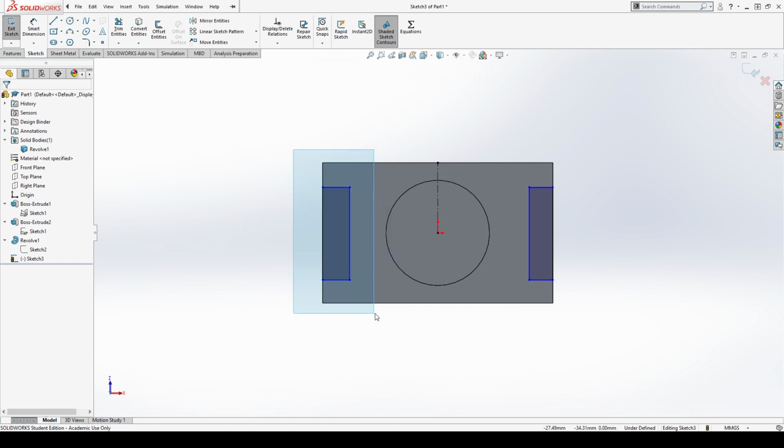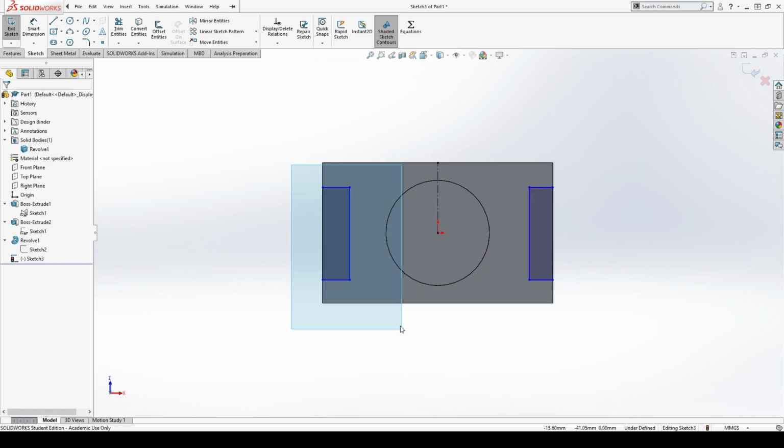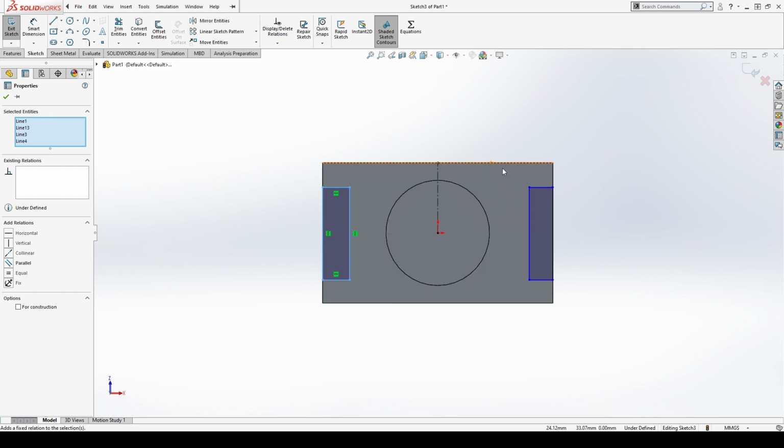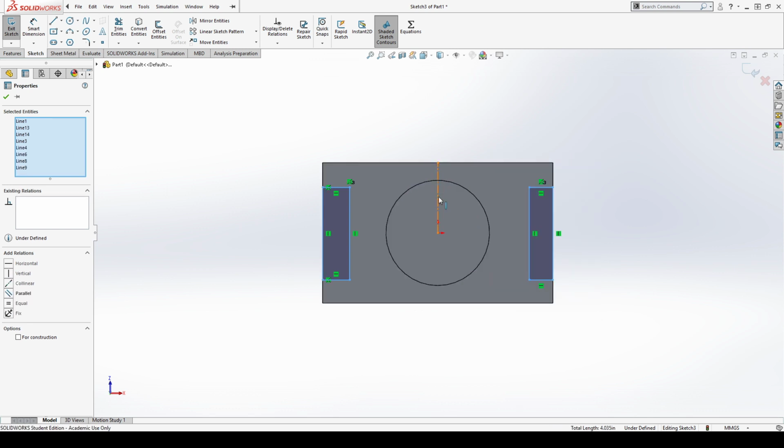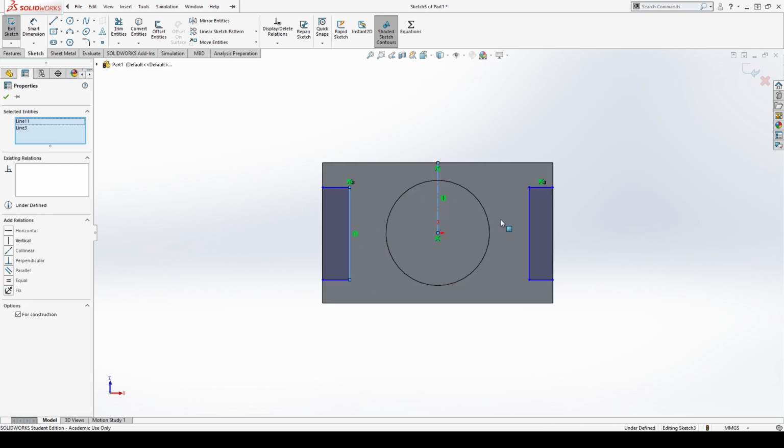Can't remember if I talked about symmetrical relations in class here. I definitely talked about them in my rambly stream last week. So let's talk about those, and the center line. I guess I can't do that, I have to do it two at a time. So these two lines and a center line, I can make them symmetric.